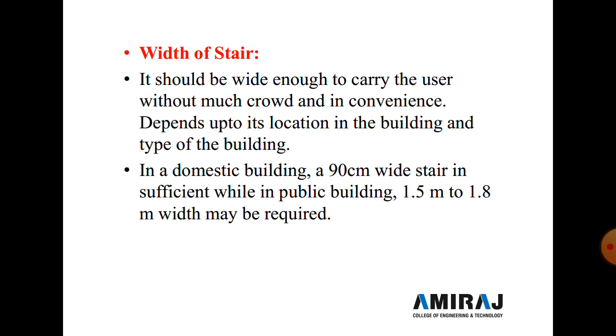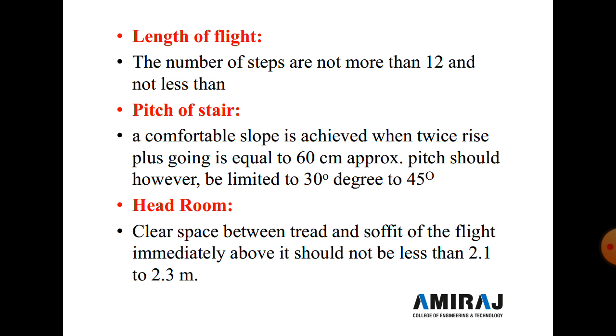In a domestic building, a 90 centimeter wide stair is sufficient, while in a public building 1.5 meter to 1.8 meter width may be required. So these are the general requirements of the building. Then, after the general requirement, we apply the length of the flight. The number of steps should be not less than 12.